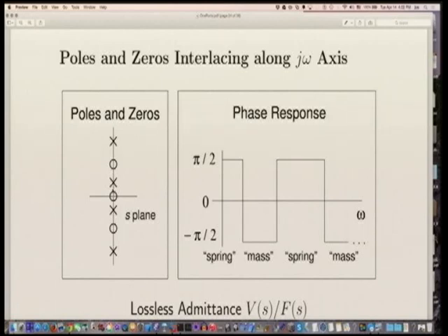So I'm here between this zero and pole, and I can see I've got a plus 90 degrees from the zero, and then I have a minus 90 degrees from a pole, but that's canceled by the plus 90 degrees from this pole, and then I can pair up these zeros and poles, and they just have canceling contributions, right? So I'm sitting here at a plus 90 from that DC zero, all right? And so here I am.